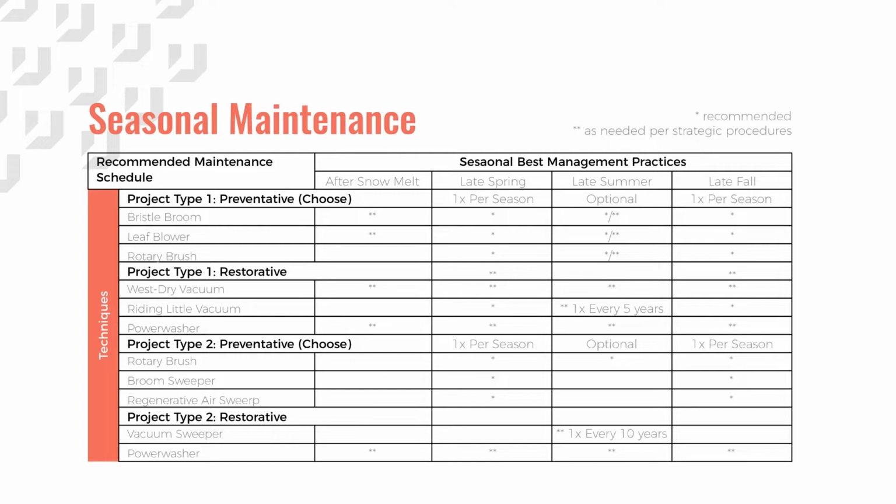After the snow melts, March 1st to April 15th, begin using a broom, blowing equipment, or a rotary brush to clean the surface of the unit paving. Give special attention to areas used to stockpile snow. Once this is complete, replenish the joint aggregate. Every 5th year, vacuum or power wash problem areas and refill the joint material.